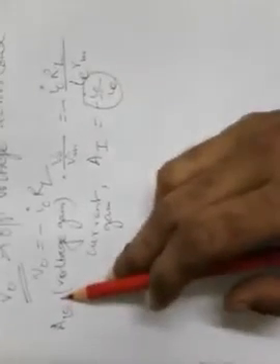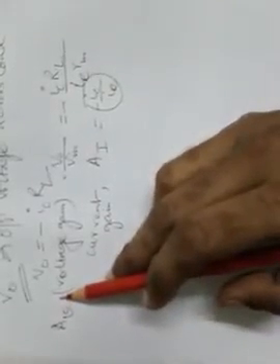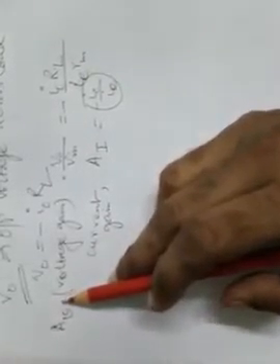If RL is much higher than Rin, AV will have a considerably larger value than 1, so it will establish a sizable voltage gain by the transistor amplifier. So that's why we can say that a transistor can work as an amplifier.